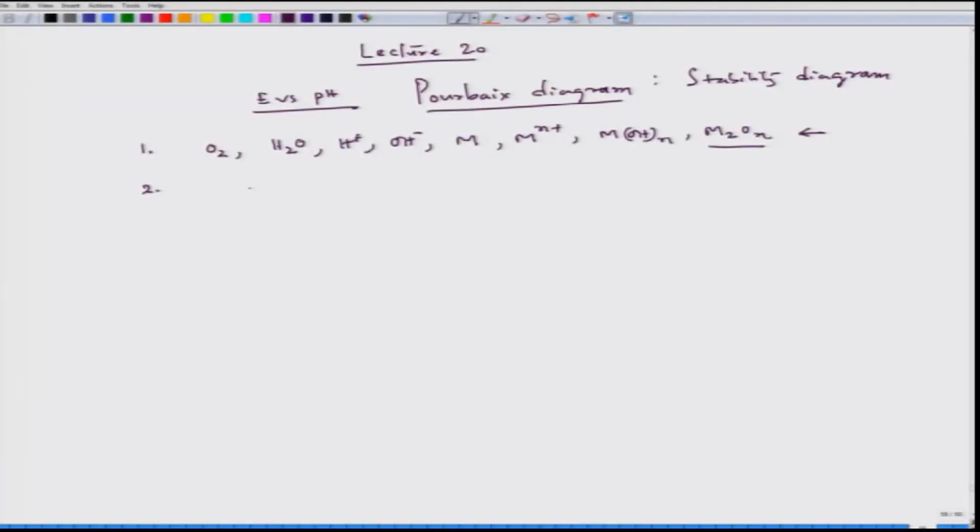So, let us categorize those reactions. One reaction, for example, in water sometimes we have dissolved carbon dioxide that can react with H2O and form H2CO3. As I have said, this reaction cannot be plotted in the Pourbaix diagram of a metal, but this is a weak acid, and still it would lead to a certain pH of the system that can affect the corrosion stage.